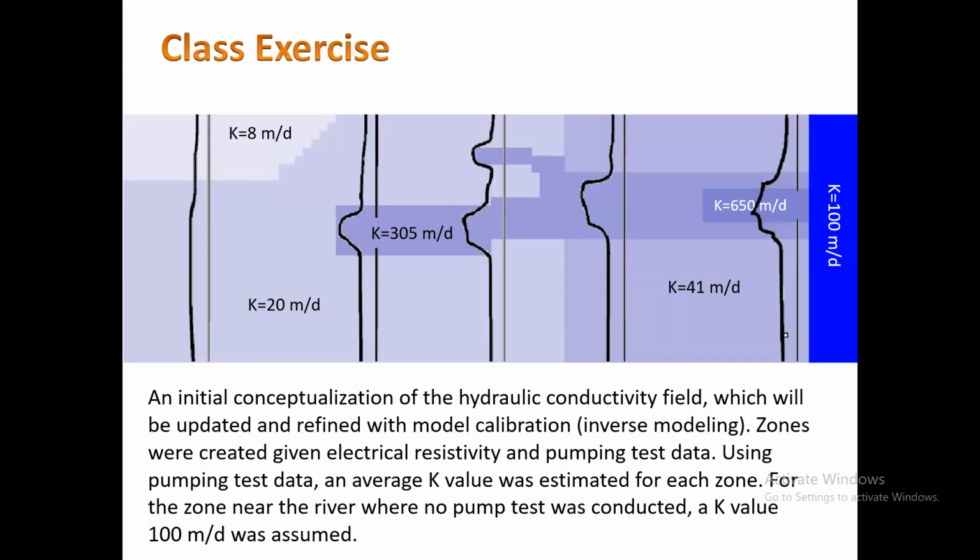So basically I have to define these boundary conditions. That's what I give to MODFLOW. I give MODFLOW these boundary conditions and these K values, and then MODFLOW will tell me the H at each cell or each node, depending on what flow you're using. Okay.